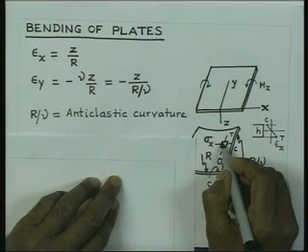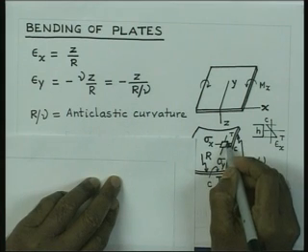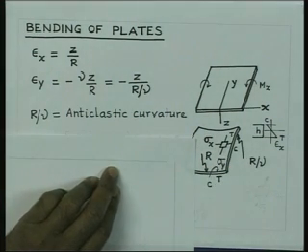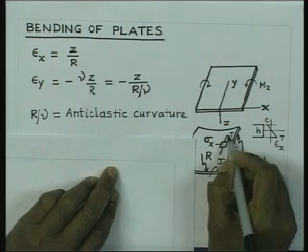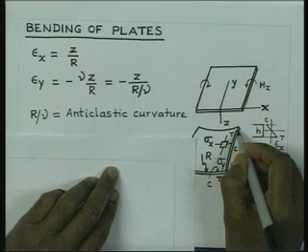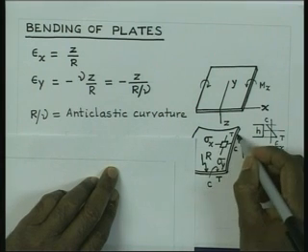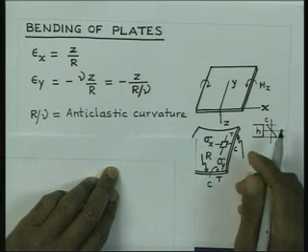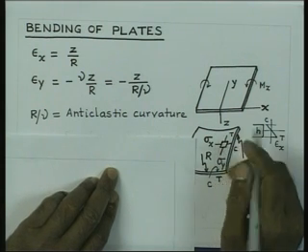So, what you find here is that as you consider an element on the surface of the plate, there will be stresses in the x direction, there will also be stresses in the y direction. Now, this tendency of curving like this is prevented towards the center of the plate. So, there is no such curving at the center of the plate, and you find that these stresses are going to actually come up here in the y direction as well.